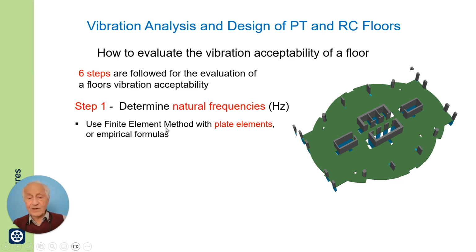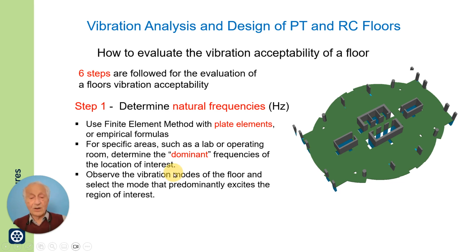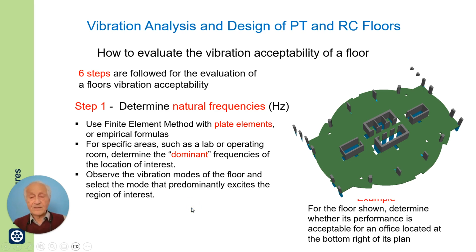You use a program today which is based on plate elements. Plate elements in bending; it doesn't have to be a flat shell element, just bending will do. A finite element with bending plate formulation. You define the specific parameters of the floor, such as whether it is an operating room and so on. Then you observe the modes of vibration from the program. The program gives you the modes of vibration, and then you select the mode that is dominant as far as your location of concern is important.